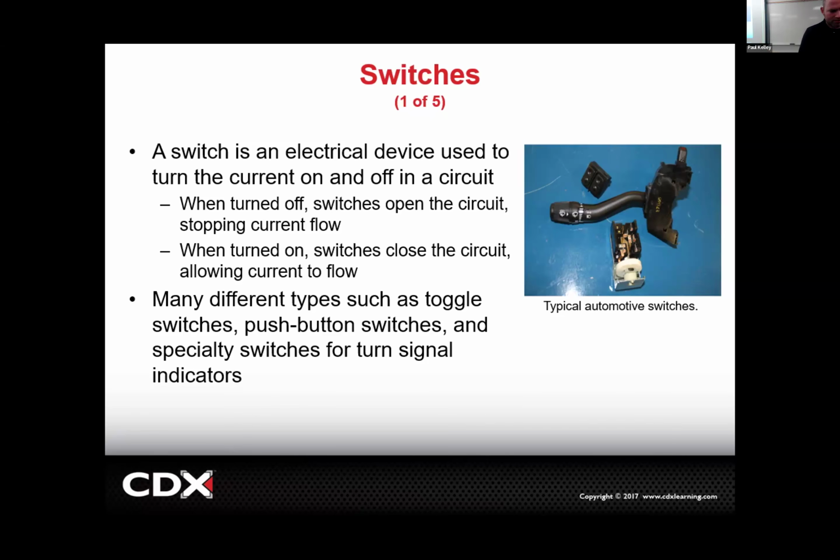And then if you get into, let's say, this type of switch that we'll call a multi-purpose switch or a specialty switch, that can have all sorts of stuff going on. So technically, just this turn signal switch alone has the headlights, it has the windshield washer, the windshield wipers, sometimes the turn signals. There may be no less than 10 different switches inside of that switch assembly.